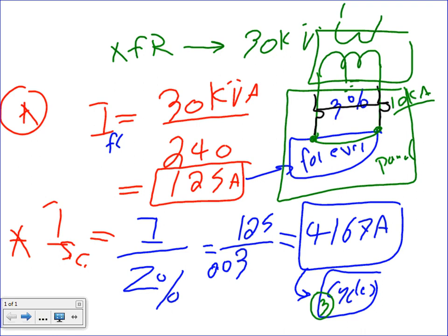There's also special occupancy and capacity. If your system is more than 2,000 amps, the utility can, on request, give you two services: one service of 2,000 amps from this side of the building, another 2,000 amps from the other side. For special buildings with special occupancies, where you need two voltages, you can ask for a 208 service from this side and a 480/277 from this side. No problem, bring it on. They can give you that. So I want you guys to highlight this, very important. The second one I want to do is page 74, please.